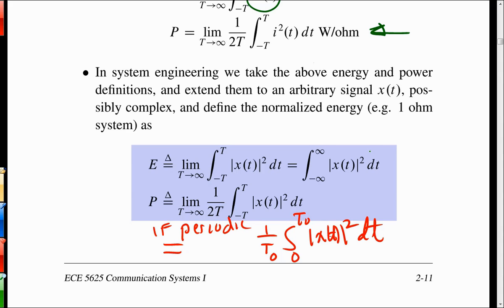And this is where I made some observations last time, and then I'm going to say some more. Energy ends up being easily calculated in this form. Just integrate from minus to plus infinity for finding the energy, but finding the power, you have to take the limit, because you just can't integrate from minus to plus infinity and cope with that being infinity all at the same time. You have to do it in stages.